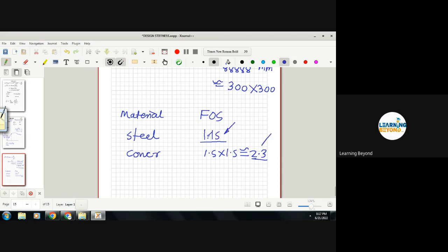The factor of safety for concrete is more because it is made up of cement, aggregate, sand and water, and you cannot assure the same quality of concrete everywhere because the aggregate and sand are different at different locations. The second criterion is the shape, because we test concrete in the lab using cubes and the real structure is different.